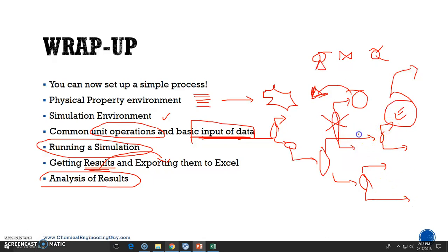So also, why do we need to pressurize that? Why was the compressor that high? Why do we need 5 bar? Maybe you can ask yourself, maybe the client requires this at 4 bar and I am adding 1 bar in order to avoid pressure losses. So let's go and check out why there is a lot of pressure loss. I don't know, there are plenty of things you could be thinking on, and this is the importance of the engineer. That's why a computer will never replace an engineer, because engineers will think outside the box. You need to go further.